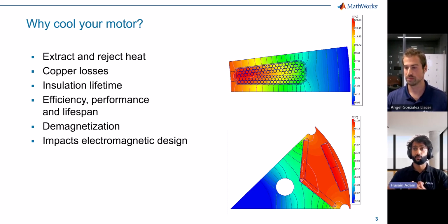We look at NVH to analyze noise and vibration. We do mechanical stress analysis to ensure the machine has structural integrity. And just as importantly, thermal analysis, which will impact the machine performance and its lifetime. So as the motor operates, heat is generated internally within the windings, within the magnets, within the stator and the rotor, and the effectiveness of the cooling design in extracting that heat and rejecting it from the motor determines the continuous performance of the machine.